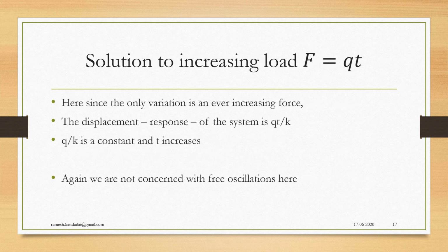Similarly, for a continuously increasing load where F is equal to Qt, where Q is a constant. As time increases, the load increases. In this case also, the deflection happens at any instant in time depending on the value of F, and it is equal to the load F divided by the spring constant K. We are not concerned with free oscillations here also.